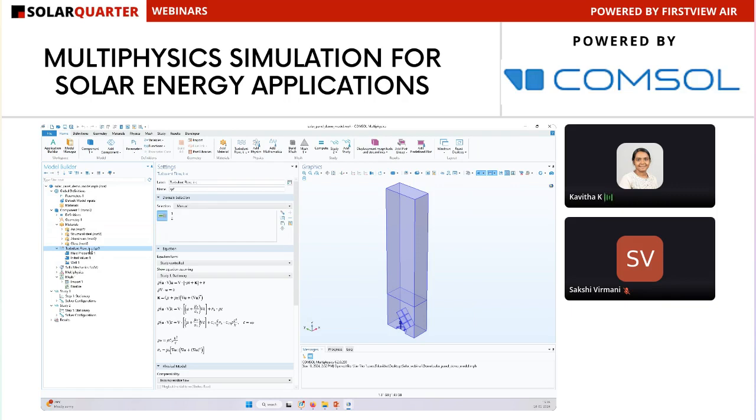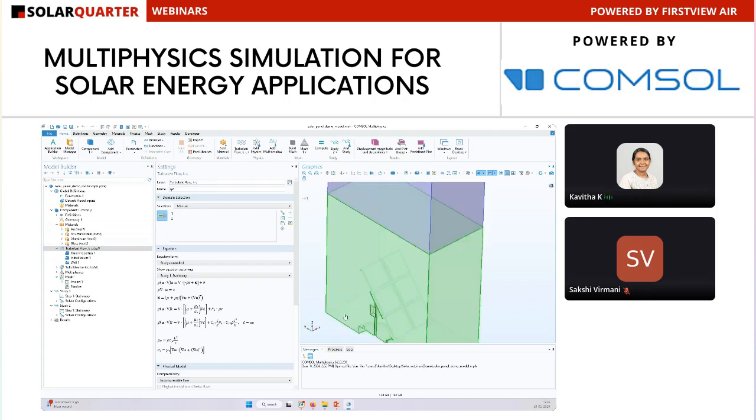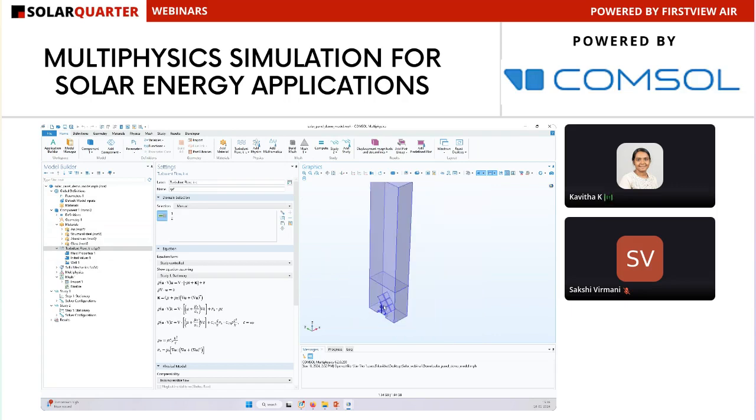Here in this example, we are modeling a unit cell, and this solar panel is going to be periodically placed in a solar farm. We have also included only half of the panel structure instead of the full panel, so we can use the symmetry condition to save on computation.